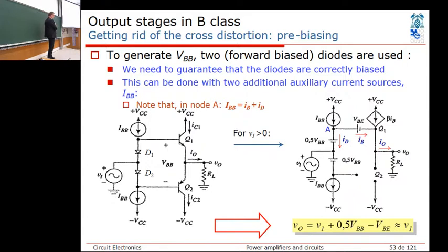How you can match those properties? One way is to actually have a matched NPN pair so that you're using that part of the transistor here. That's a trick that dinosaurs used, ancient times. So that's actually just the base and emitter of a similar transistor.